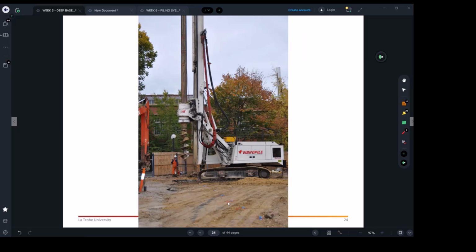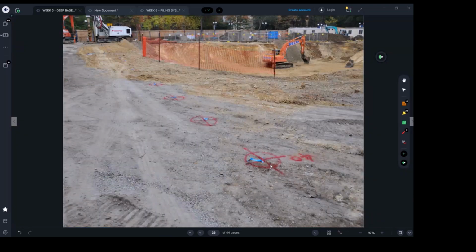Now, first thing, they're going to specify where the holes are going to be according to the engineering documents. And this is the CFA construction method, which we will talk about next week. This machine is going to excavate, go 9 meters into the ground, whatever, and pour the concrete as it goes up. As it goes up, they're going to submerge the reinforcement inside it. Just a picture here showing you the holes correctly located and surveyed. This is all done by a licensed surveyor. You're going to ask him to come and position them in the right spots. So it's all going to look perfect.